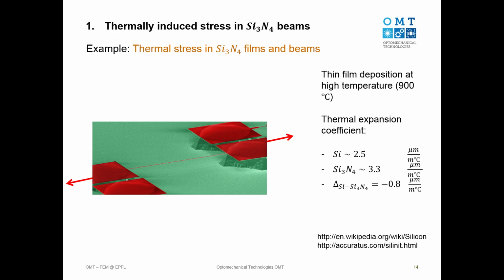So this is okay. At 1,000 degrees, these two have basically the same radius in a wafer. The problem starts when you start to cool down. Obviously, you want to take it out of the furnace. And fortunately, for my case, because I can do a PhD on it, the thermal expansion coefficients of silicon and silicon nitride are vastly different. So when they cool down, silicon shrinks less than silicon nitride does.